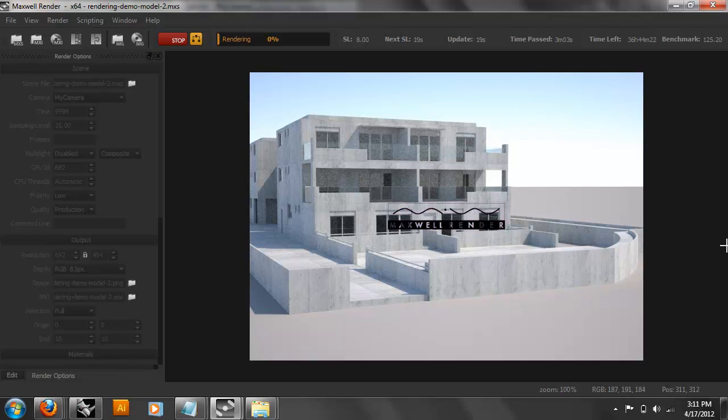Now we'll talk about ground cover and what's going on with this model. If you're seeing this, this ground that I drew is just a plane and the model is sitting in it. It's not very clean. That's why you're not really getting shadows on the edge of this, because it's not able to resolve those intersections very well. This is not a clean model. This is not a good model. So your model has to be well crafted.